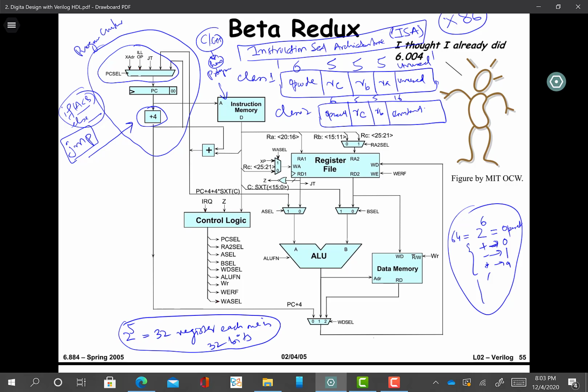So sometimes the mux will be feeding PC +4. So this is the PC +4 line, and sometimes it is doing something else, which is coming from this line and it is going here. So you see this adder. We are adding something: the current program counter, and then there is some offset that is coming from somewhere else. So this is how you implement maybe PC +100, for example. So it is coming from here. So this is the purpose and life of the program counter and instruction memory.